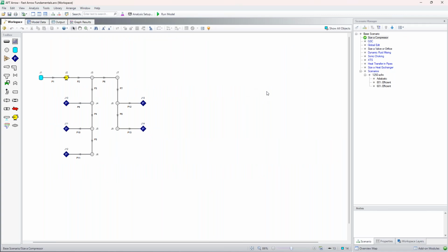All right, so getting into the software, this is the model that we're going to be building. I'm not going to build this entire thing in front of you, but for those who are completely new to the software, we have a drag and drop interface. So if I were to build this model, I would start by dragging this tank, this compressor. If I double click on these icons in the left, we call these junctions, it'll keep it active in the workspace. So if I wanted to lay out all of these branches here, then I would be able to build the model like that. And then you just connect them simply by drawing the pipes between each one of these junctions right here.